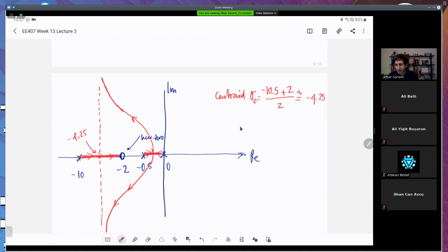So this looks like a much better configuration, because the asymptote is on the stable side. That means you can increase the gain as much as you want. There will be some consequences, like overshoots will increase and so on, because you are moving along the frequency of oscillations.